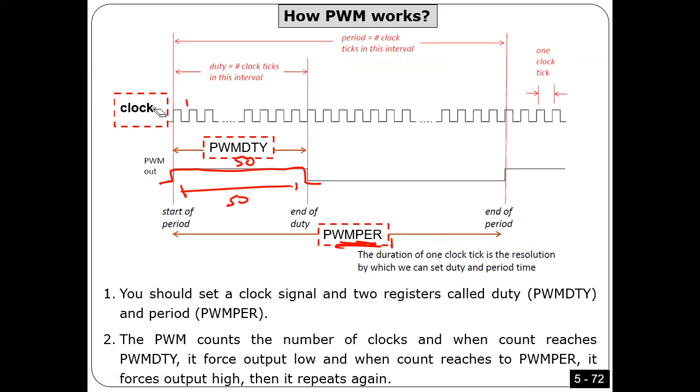So I have a clock. This clock, I'm gonna use it like a reference, and then the number I write here, for example if I put here 100, means the time from here to here should be 100 cycles. Is that okay? That's why I'm saying, if you want to change the duty cycle, all you have to do, very, very easy, just change this number.